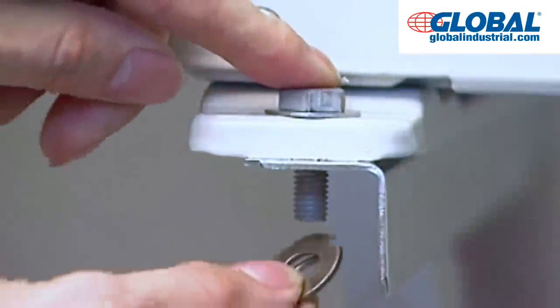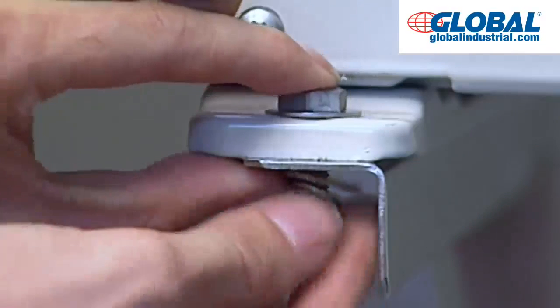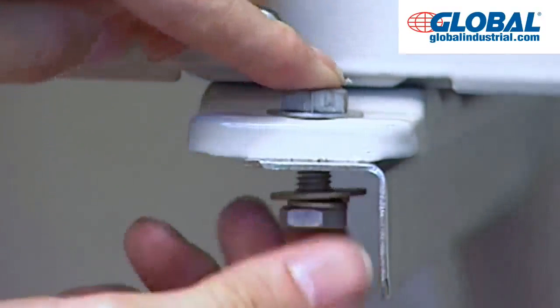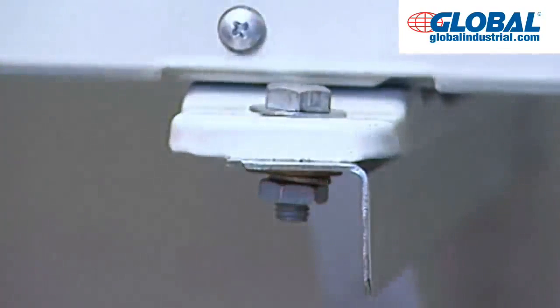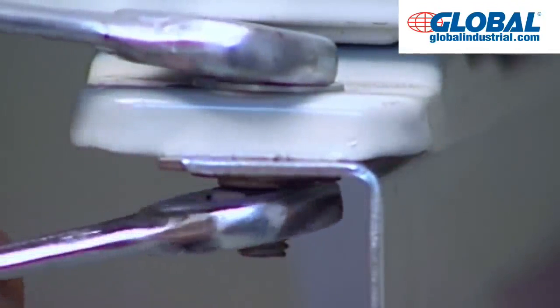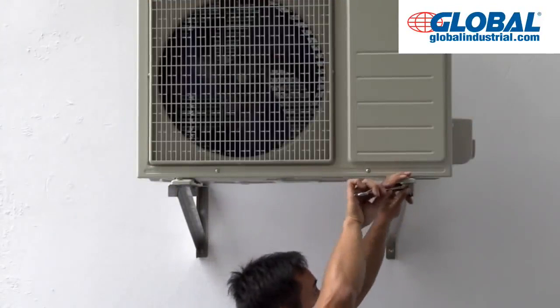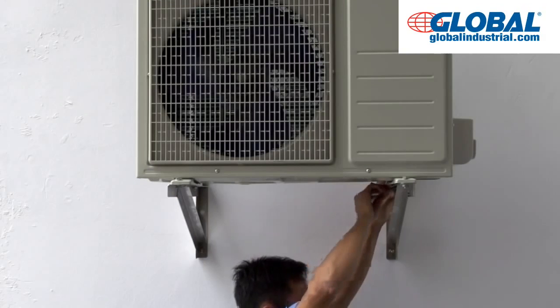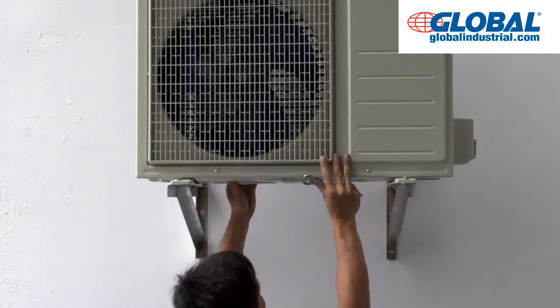Align elliptical hole of foundation bolt with fastener hole of bracket. The outdoor unit is fixed on the bracket by 4 bolts. Bolt is threaded from up to down and is tightened by adding check washer. If allowed, rubber gasket can be added to reduce the vibration of the outdoor unit during operation.